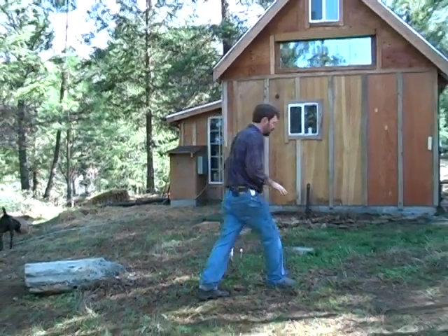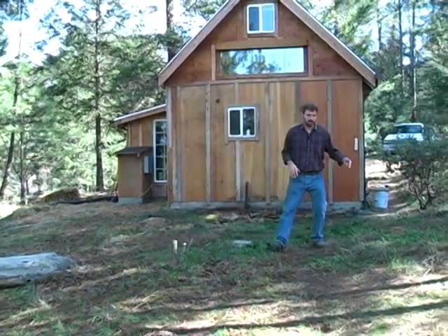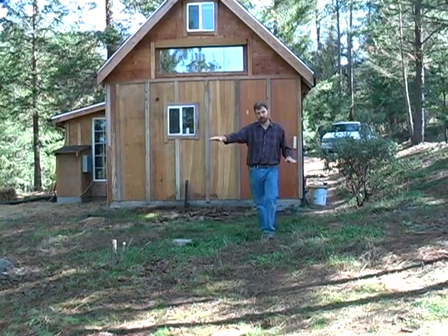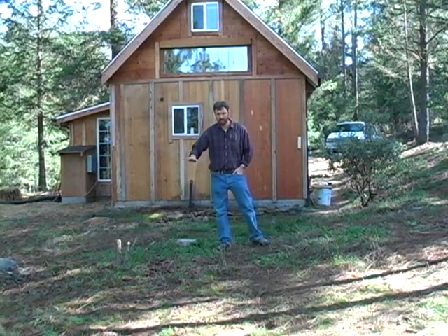The first thing you want to do is called a site evaluation. Basically what that means is you want to go to the area where you're going to be constructing your slab and look at what obstacles might be in the way of that construction. Now on this site we have some elevation issues we need to deal with. This side of the slab over here is about 2 feet higher than the far corner. So when we do our excavation, we're going to make sure that we can level this out without creating any drainage issues for the slab.